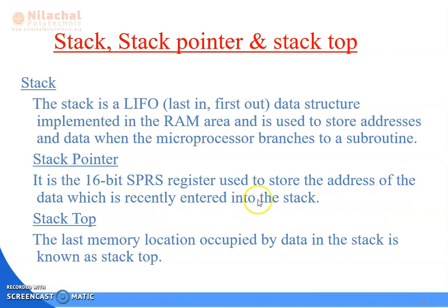Next is stack, stack pointer and stack top. So first, what is stack? The stack is a LIFO, that is last in first out data structure, implemented in the RAM area and used to store the addresses and data when the microprocessor branches to a subroutine. Then stack pointer.